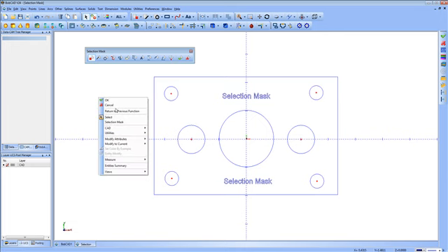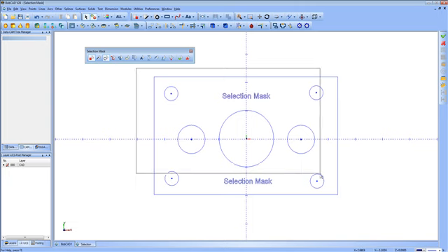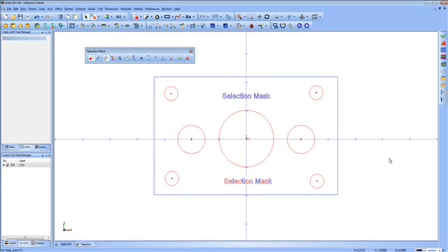Let me go ahead and right-click and hit Cancel, and let me come back up here, go back into selection mode, uncheck everything, and this time we'll click the points and circles. Now I window pick the entire part, and you can see that I have only the points and the circles selected. The vectorized text down here also selects because there are arc segments in that particular part of